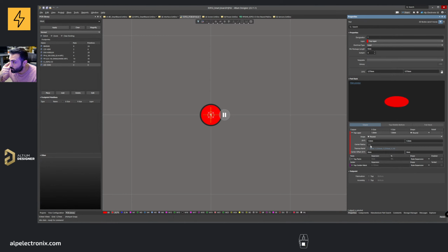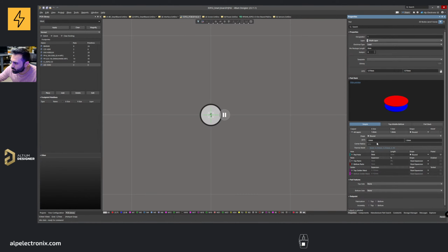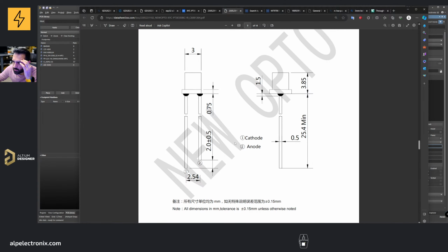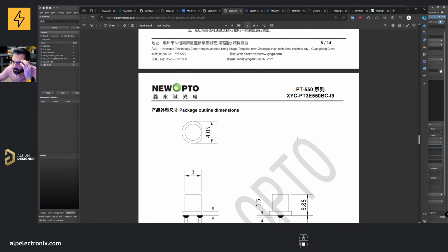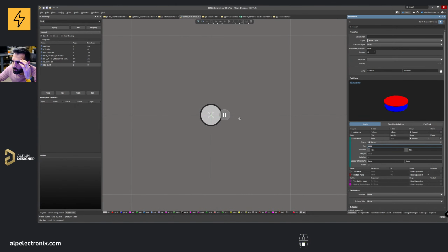This should be multi-layer. If it is top layer, it means it's SMD, and then it will not show you the hole, basically the pad hole. Yes, but let's check the pad sizes if it suggests anything. It says 0.5. Actually, we should make something like 0.6 or 0.65, depending on the available drill bit size. And then we don't have to have this big, or maybe 1.1.